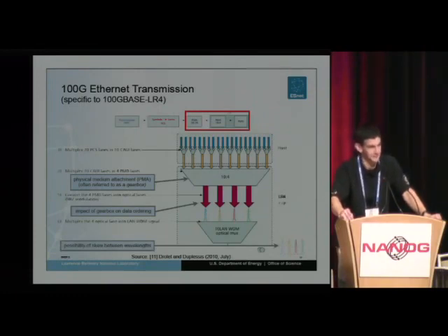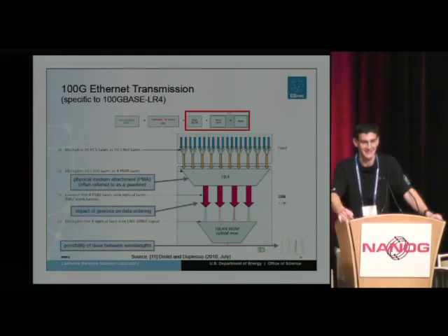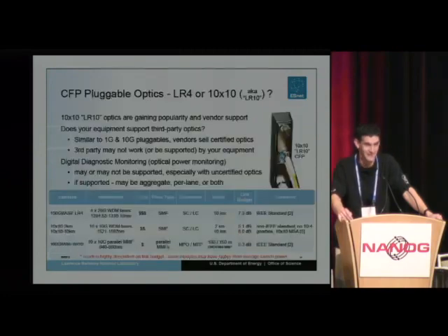And finally, this is just showing you how the 4 wavelengths, when they go onto the fiber, have the possibility of some skew, and these are all things that the receiver now needs to deal with. These wavelengths are going to come in with skew and other effects associated with them, and that's what all those SONET-like features you saw on the last slide are for, basically to give you the ability to deal with these physical effects of what happens after these signals go down the fiber.